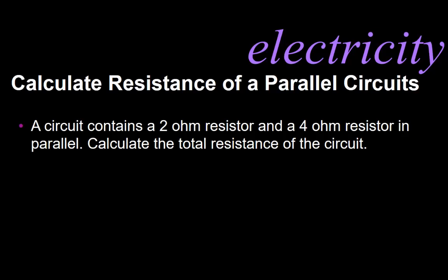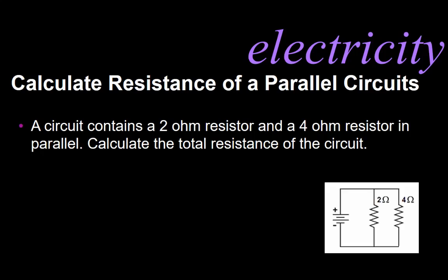We still have to have a battery, and that battery is going to give us a certain amount of drop within the system, or potential difference, or voltage. And we want to calculate the total resistance using this new formula we just got because they are two parallel pathways. So here's our drawing. In this case, we want to add them a little bit differently than we did before. So it's not R1 plus R2 plus R3. Instead, we want to calculate it with 1 over.